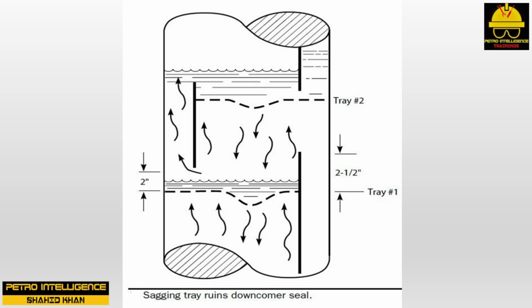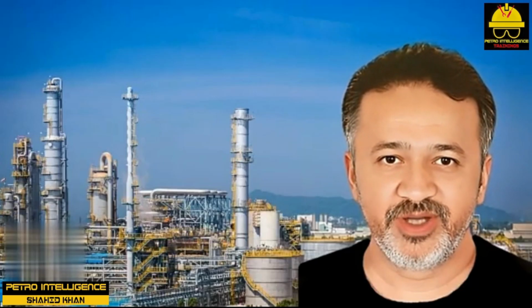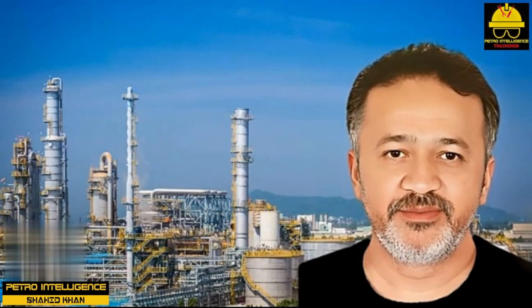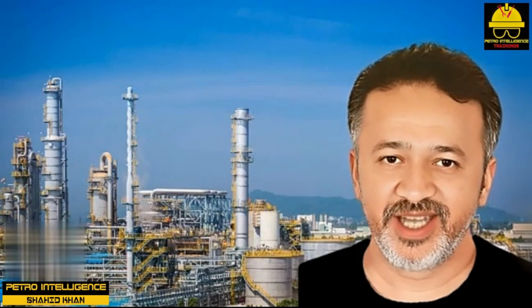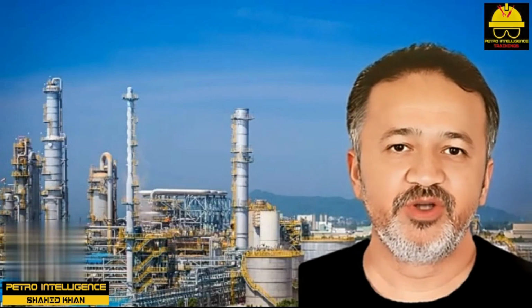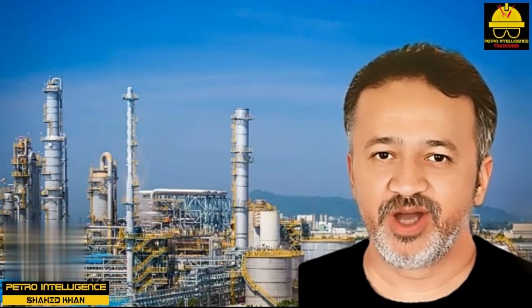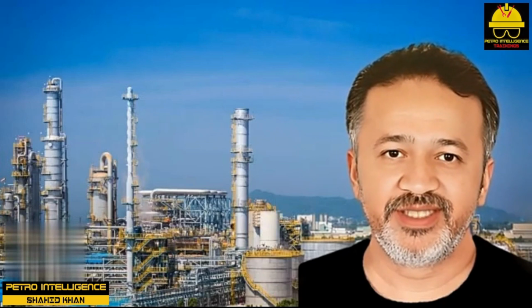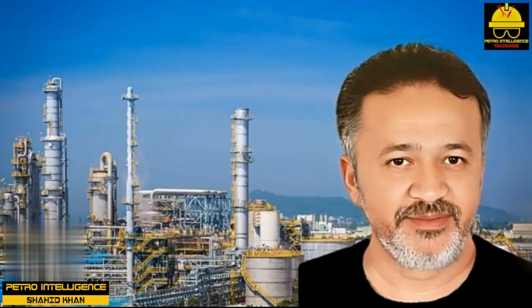Worse yet, the way one stops this flooding is to increase the dP across the sagging tray deck by increasing the vapor flow, for instance, by increasing the reboiler duty or stripping rate. This contradicts common sense that flooding is promoted by higher vapor rates. But we can stop flooding in a crude distillation tower in a refinery by increasing the stripping steam rate. Also, you can observe that increasing vapor rates in a column reduces tray dP.